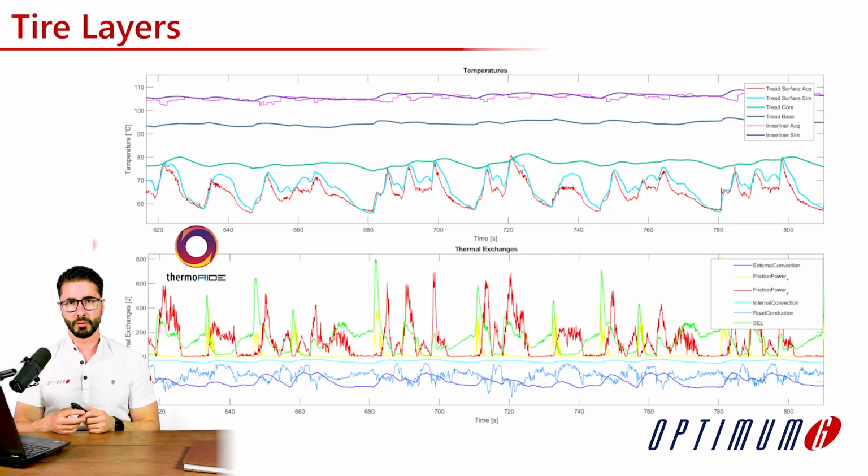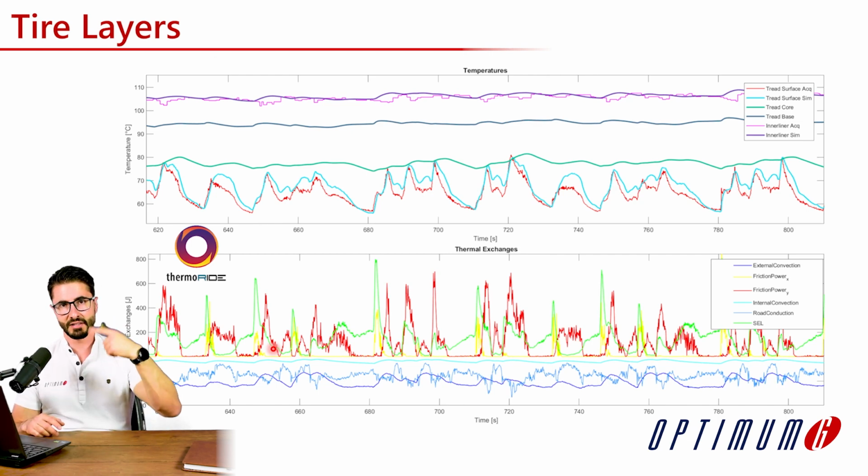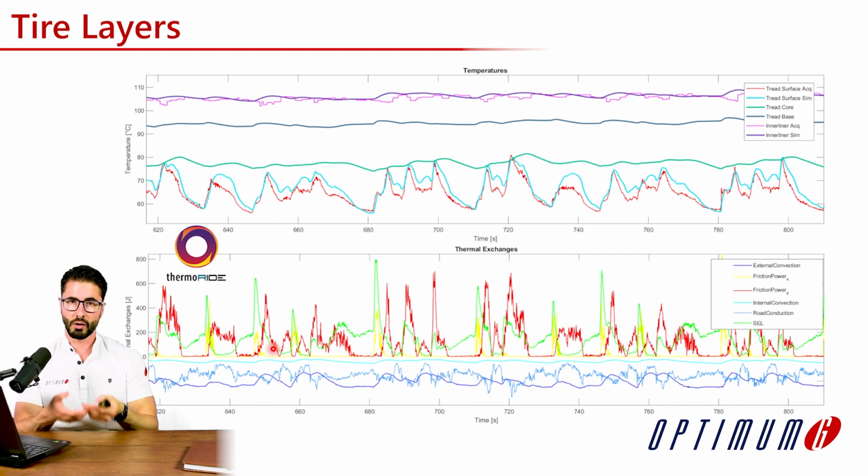It is very useful that we understand each of the mechanisms that generate tire temperature, because we can also understand that when we are at the track, if we change any parameter that will influence one of these, we'll be influencing the tire temperature. For example, if we have the car really understeery, it will slide a lot on the front axle, and then we're going to have a lot of sliding energy on the front axle, putting a lot of temperature, for example. If we decrease the pressure, we'll have a lot more tire deflection as the tire is rolling or cornering, which will also increase tire temperature, at least from this perspective of hysteresis and energy loss.